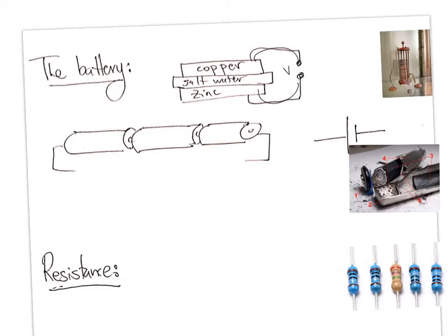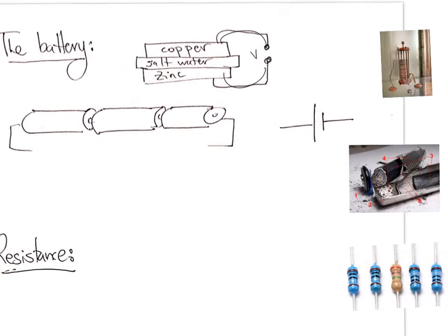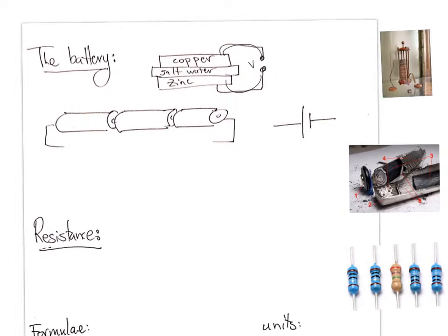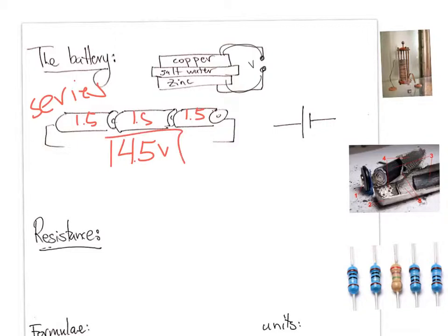You can connect batteries together. So these batteries are connected in series, we say. Not like the Apple woman. Okay, so if these were a couple AA batteries, 1.5 volts and 1.5 volts and 1.5 volts, you guessed it, combined like this, they would create a voltage of 4.5 volts. Later, soon, we will talk about series versus parallel, but for now that's all good.